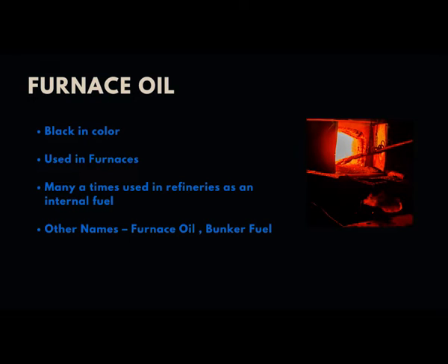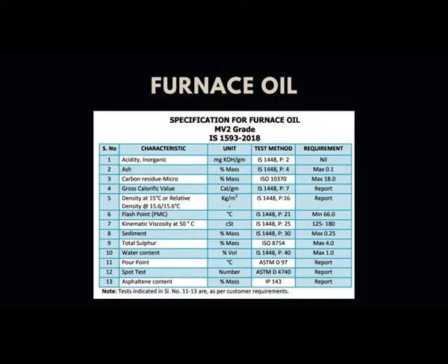The other names for fuel oil or furnace oil are bunker fuel and fuel oil. Among the specifications for furnace oil, an important one is the kinematic viscosity. If the viscosity is very high, it is very difficult to pump it from one place to another, or even within the plant or inside the burner. So viscosity is going to be a crucial test, known as the kinematic viscosity.